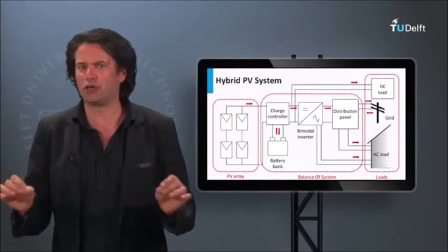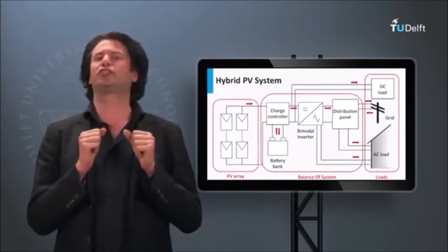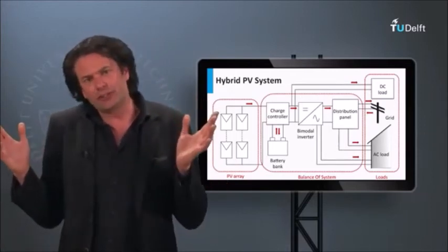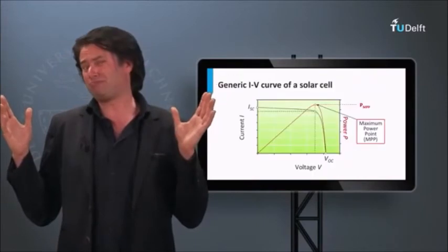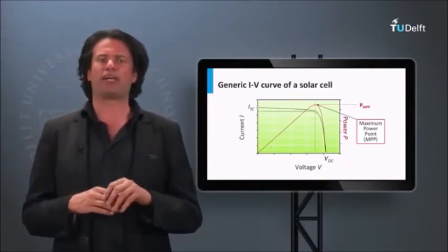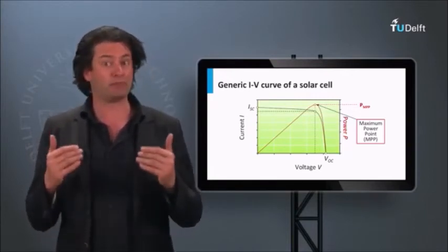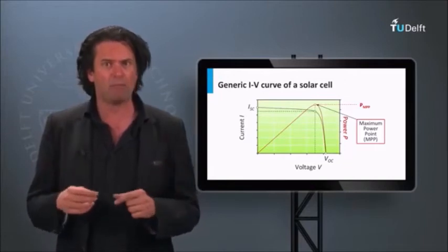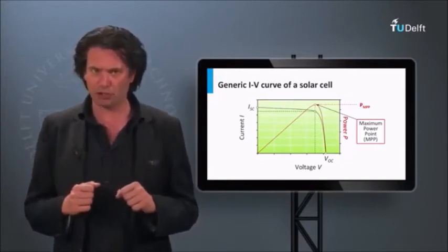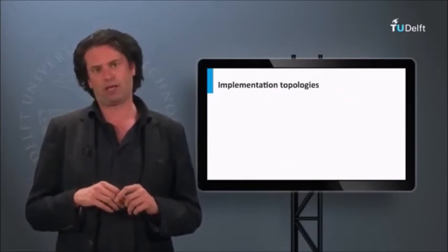Now, we already know the basic application of an inverter in the PV system: power conversion from DC to AC. Can the inverter perform any additional function? The answer is yes. Thanks to advancements in power electronics, it's common to have inverters that implement a maximum power point tracking mechanism before inverting the voltage, thus ensuring that the PV modules or arrays are operating at the maximum power point.